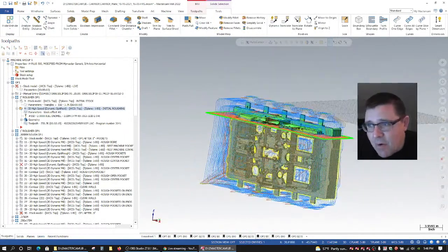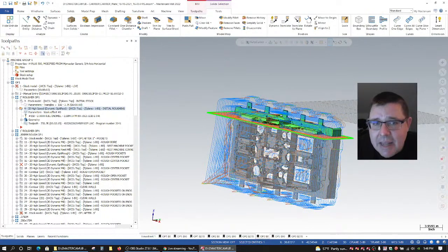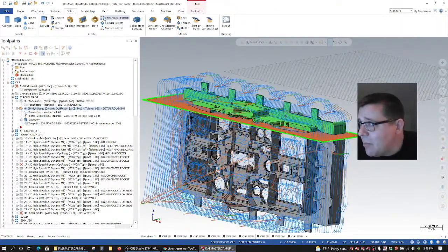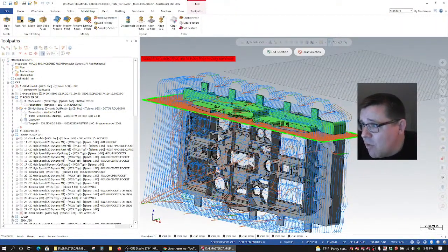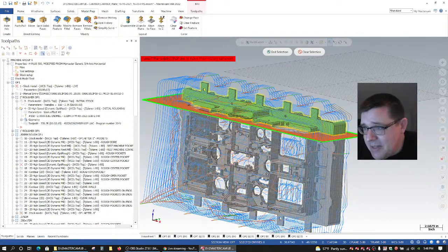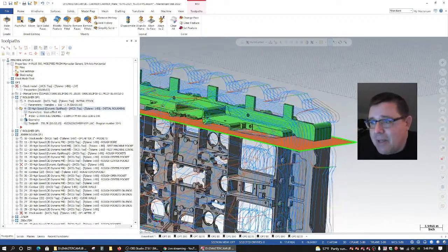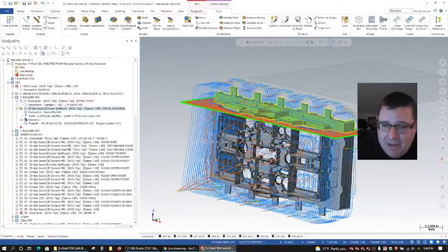But you have to remember, after you do something like splitting, you have to go back and remove history. It's the removal of the history that really helps everything. So now I'm going to go back, model prep, remove history. I'm going to take this piece, and do end selection. And again, we're removing all that history. We're simplifying everything as much as mathematically possible.